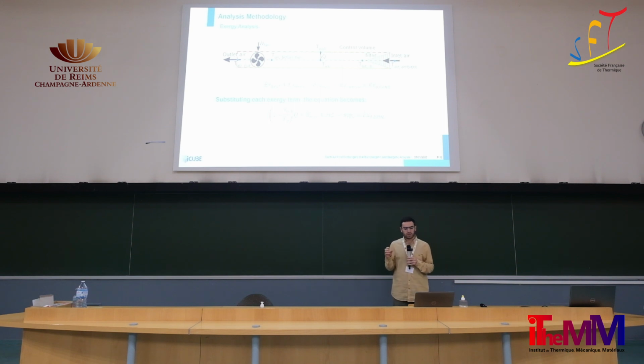You can see in this equation that exergy affects the heat transfer and the mass flow rates, but the work remains the same. And the work of the fan is just the electrical work of the fan multiplied by its efficiency. And I will also show you the equation for calculating the flow exergy, which is the exergy of the mass. This equation takes into account the temperature, the pressure, and the humidity of the air at the inlet or at the outlet.